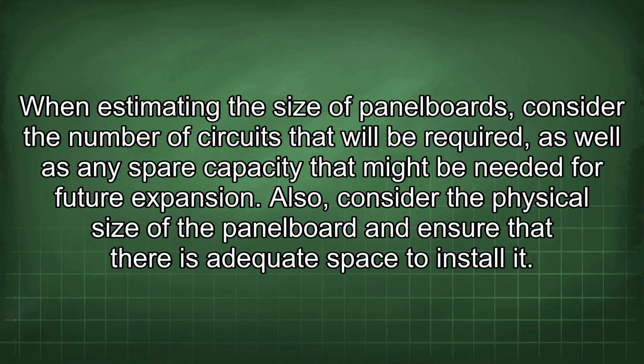When estimating the size of panel boards, consider the number of circuits that will be required, as well as any spare capacity that might be needed for future expansion. Also, consider the physical size of the panel board and ensure that there is adequate space to install it.